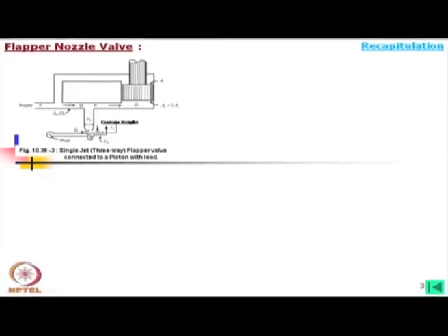That means basically it is allowing the oil to go to the rod end side of the piston, and while we are trying to control the motion of this piston, we are allowing the oil on the other hand side, but that flow we are controlling by the 3-way spool valve, isn't it? In that case, if we compare with the previous one, then oil is allowed to go into